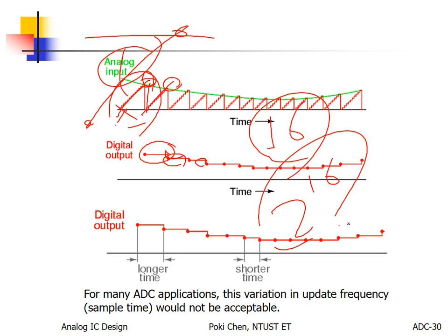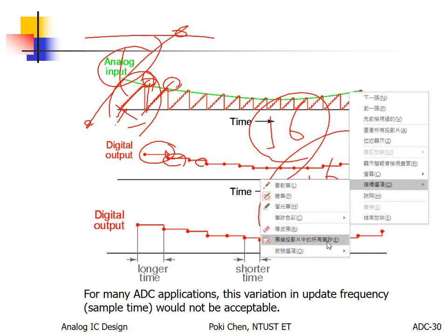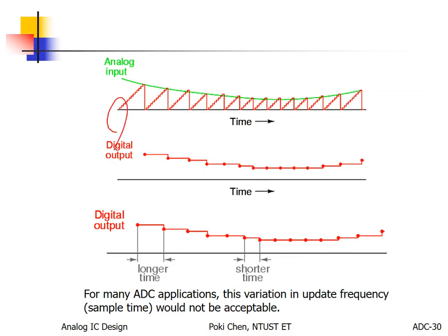The major problem is, from the beginning, after you power on the chip, you have no idea where your output is. So you need to do a reset to put the whole system into some kind of determined state. 你要把它恢复到一个你所知道的状态. So you reset everything. Usually we reset to 0. That is how we make the system go from unknown to determined. 从未知到已知.